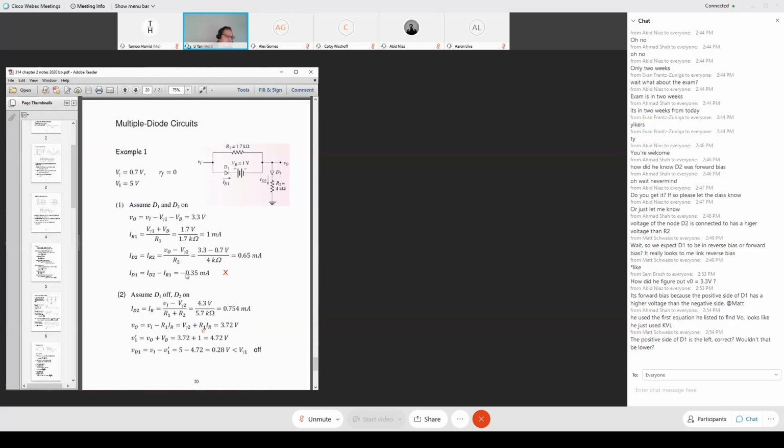Here, we trace back. Before all those equations, I made an assumption. I assumed, with my visual eyes telling me, that both diode 1 and diode 2 are on. So if I didn't make any step-by-step calculation errors and the final result is not reasonable, that means the initial assumption must be incorrect. Which part is incorrect? Did I incorrectly assume the state of diode 1, or the state of diode 2? Diode 2 seems fine; these are forward bias. Looking at this branch with this 5 volts, diode 2 should be subject to sufficient forward biasing, so diode 2 should be on.